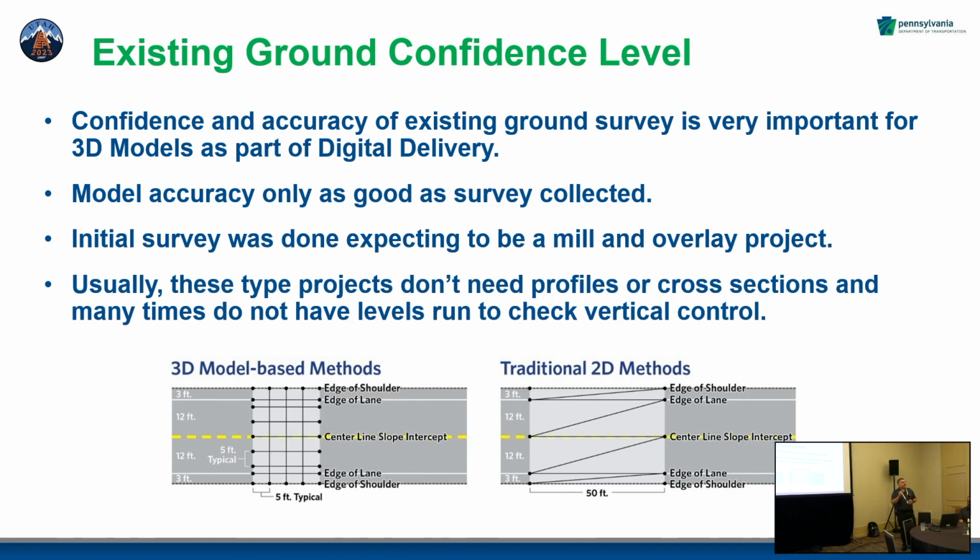That actually caused a big problem because we weren't talking to our surveyor. That group wasn't telling them, hey, I'm now going from this mill and fill project over to a model. They had to go back out and get vertical on that data, check the levels, things like that. The other thing was we wanted more density in the survey.